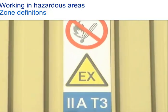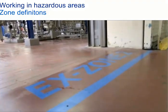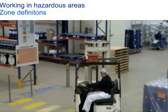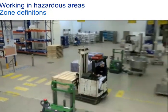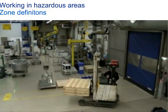Hazardous areas must be identified by warning signs and possibly also by floor markings. It is particularly important to ensure that no non-explosion-proof equipment is introduced into these zones. This requirement also applies to industrial trucks and tools.